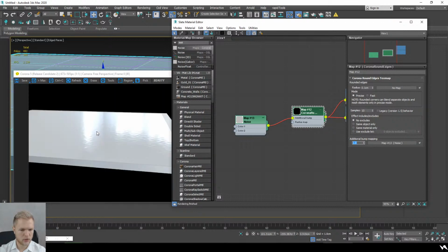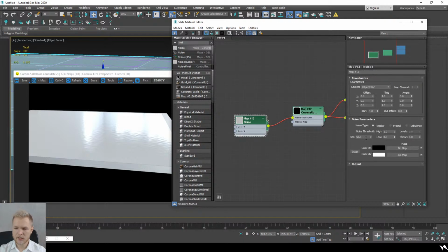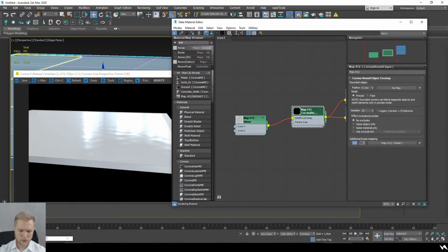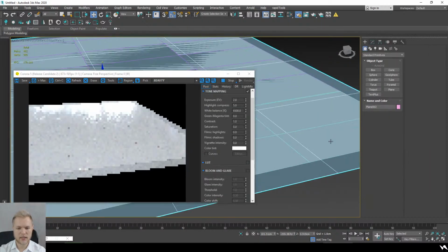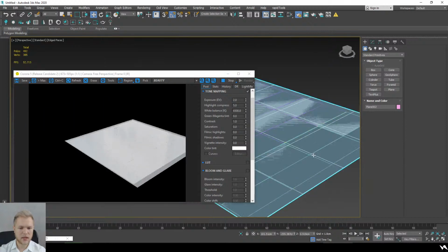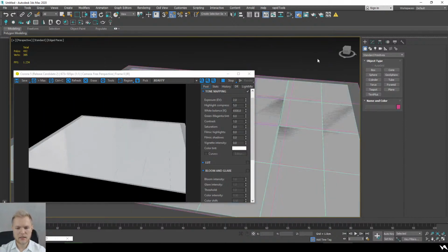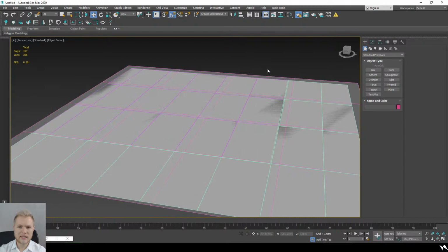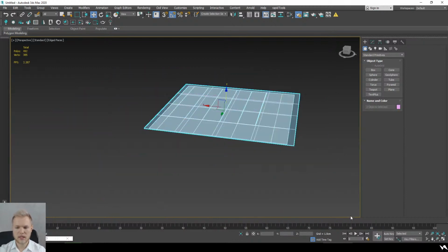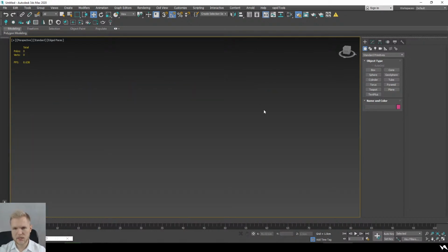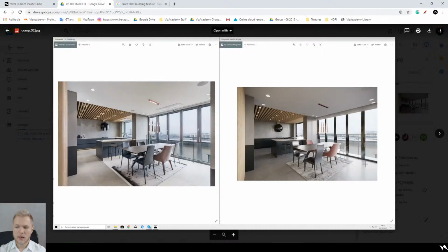We don't want your tiles to look like this unless those are that kind of tiles. But let's go for something like 150. So it's going to create this pond-like effect. And additional bump, again, we're just going to go for 1 point. And now we have this nice wavy effect. With multi-map, it's going to be even better because it's going to be randomized. And this is pretty much how you can do it. This is the easiest way. There are other methods that require a little bit extra steps. But as I said, we're always going for the most efficient way.